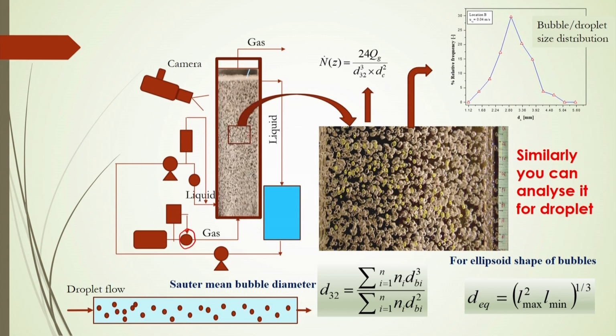As a dispersed phase, carbon dioxide gas bubbles and air bubbles will be coming out, and those carbon dioxide gas bubbles will be flowing through this column, and during that flow, since carbon dioxide gas has some interfacial area between the bubble and the liquid, through that interfacial area the carbon dioxide gas will be absorbed or transferred from the carbon dioxide gas bubbles to the liquid medium.